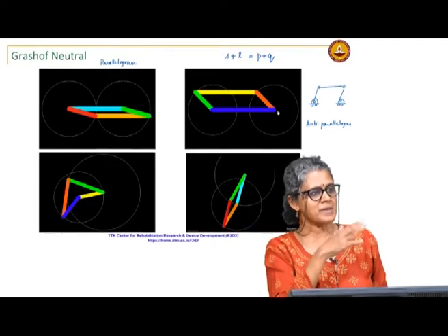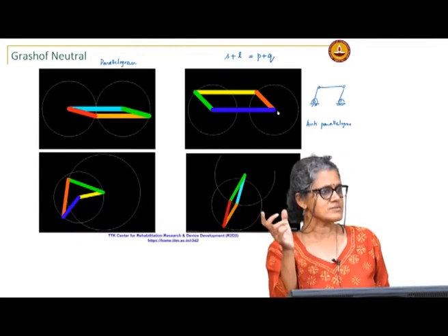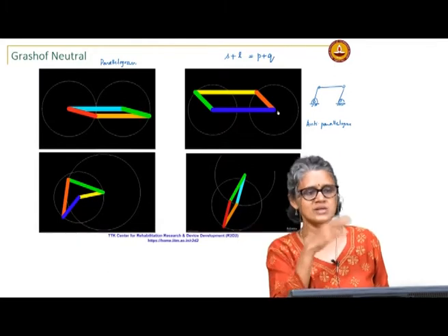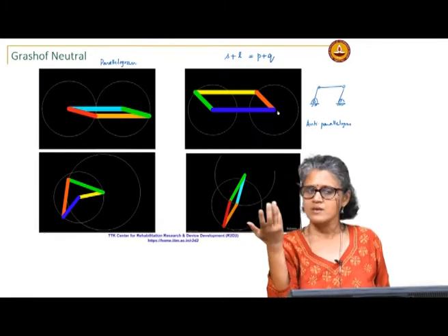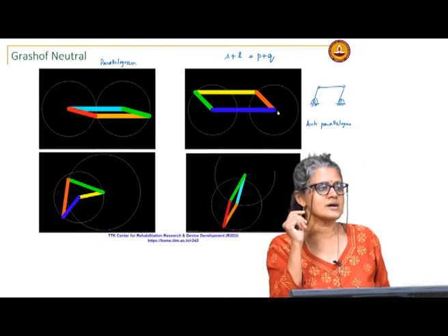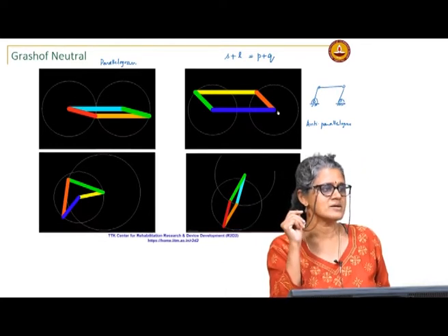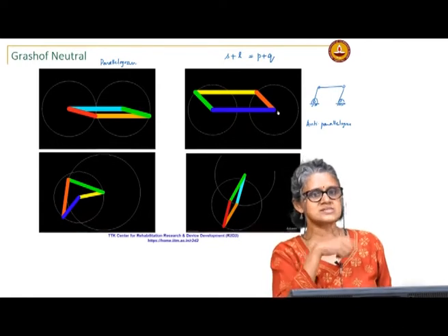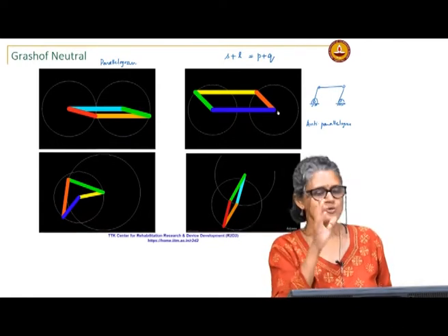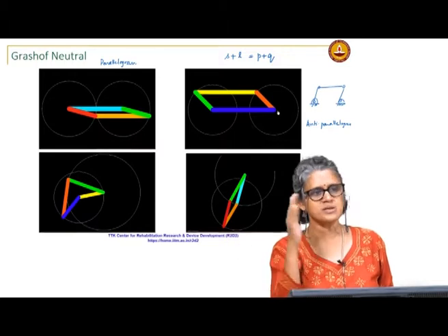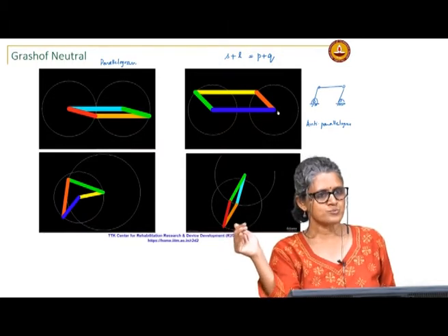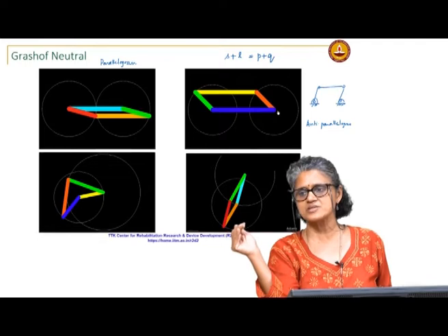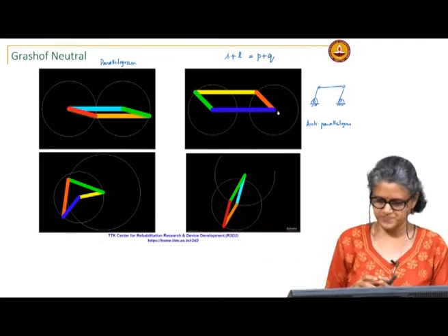So, if you need the parallelogram action only in, say, a rocker fashion, you are perfectly justified in using that between those limits. You do not have to necessarily run it through the entire range, you will still get the duplication of the input motion in the output motion. It all depends on the application that you need.